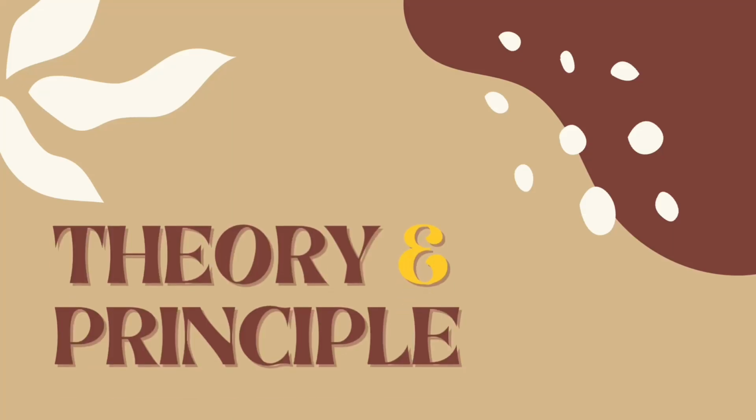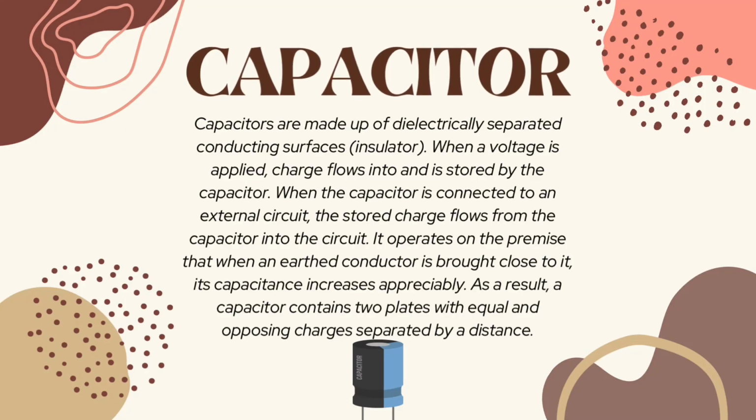I am Nurul Afifah and I will tell you about the theory and principle first. Capacitors are made up of dielectrically separated conducting surfaces, insulator. When a voltage is applied, charge flows into and is stored by the capacitor. When the capacitor is connected to an external circuit, the stored charge flows from the capacitor into the circuit. It operates on the premise that when an earthed conductor is brought close to it, its capacitance increases appreciably. As a result, a capacitor contains two plates with equal and opposing charges separated by a distance.